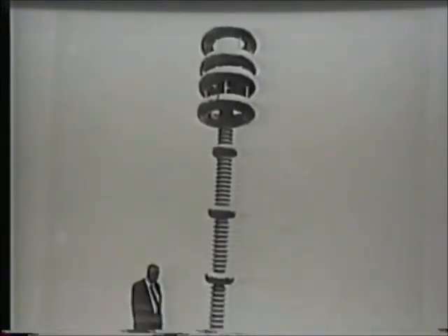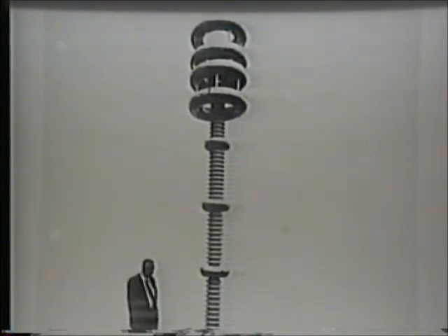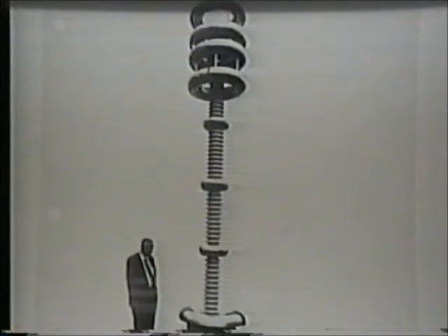Okay, in conventional measurement of high voltage, you have to use voltage dividers in order to get your instruments to work for you. As the voltage gets higher, these voltage dividers get quite large. In this case, in order to use conventional measuring instruments, this thing is more than 9 feet tall, and it's good for less than 1 million volts. So you can measure up to 1 million volts with your regular measuring devices by using this divider to bring it down to where your instruments can work with it.